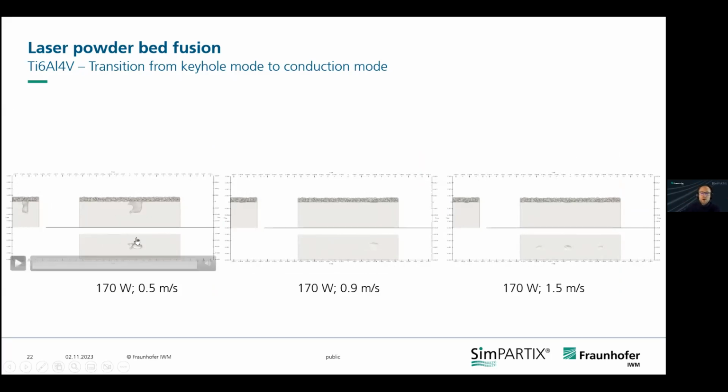So what we want is that this top layer of powder is supposed to be fused together with the substrate. If we have the deep hole as in the left example here, this is not what we want, because we get these inclusions. Inclusions mean porosity. Porosity means less dense, and this will rather lead to corrosion, to failure, to reduction in life expectancy.